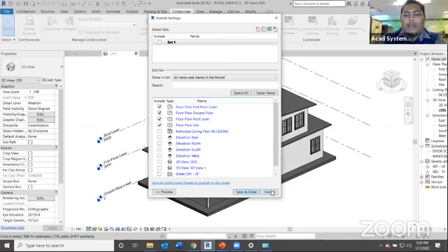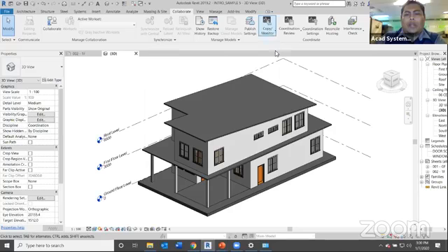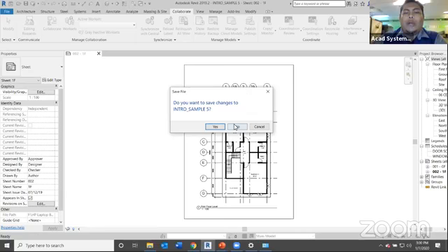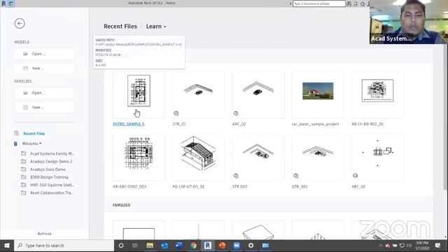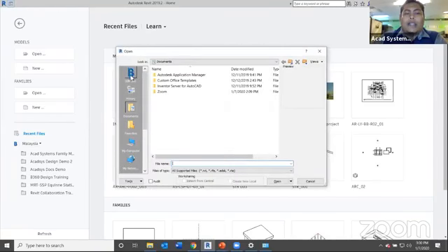And we're going to save and close. So let's say you have uploaded the first file, and how are we going to start working with the central file? Let's say this is Revit 2019.2. If you're going to start working directly from BIM360, not from your server, you can simply open the file, and there is a folder here, BIM360.